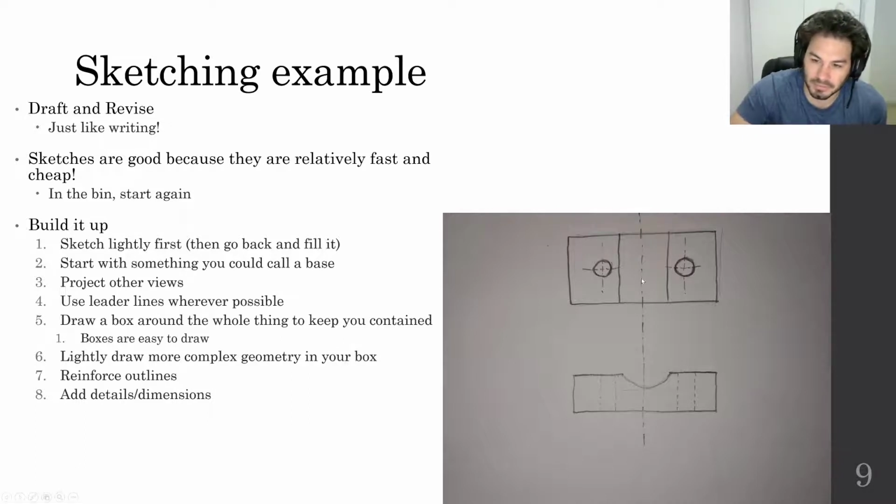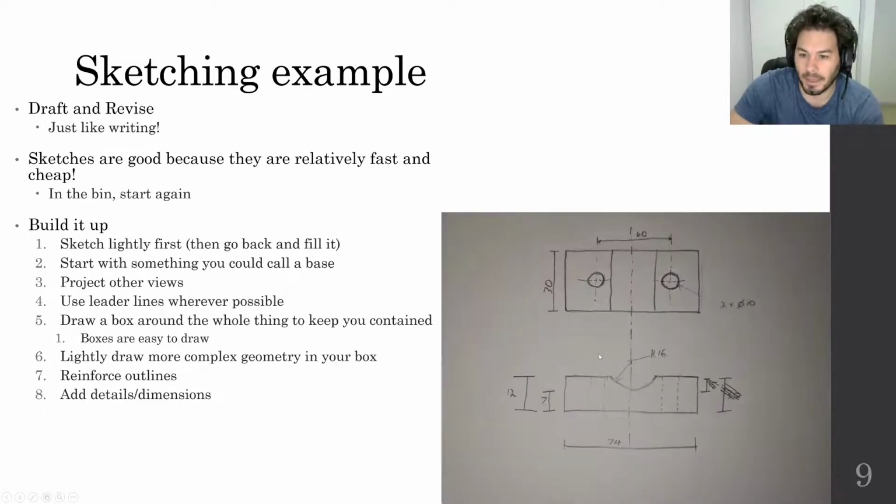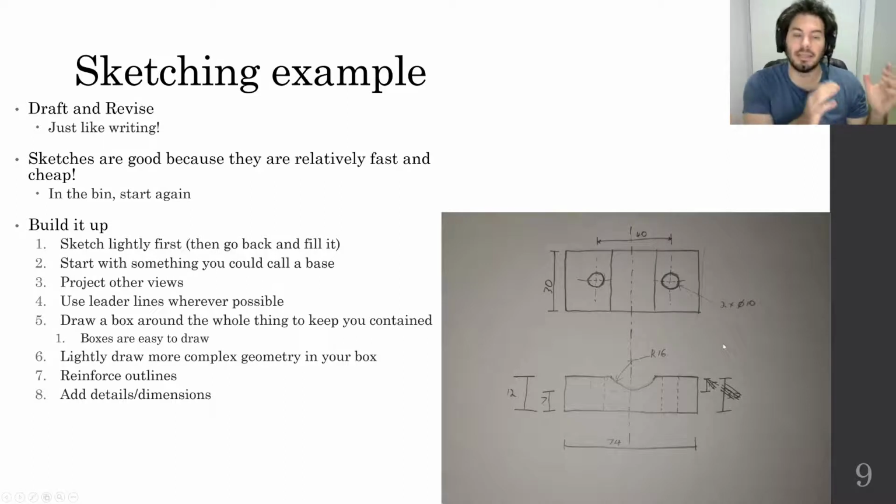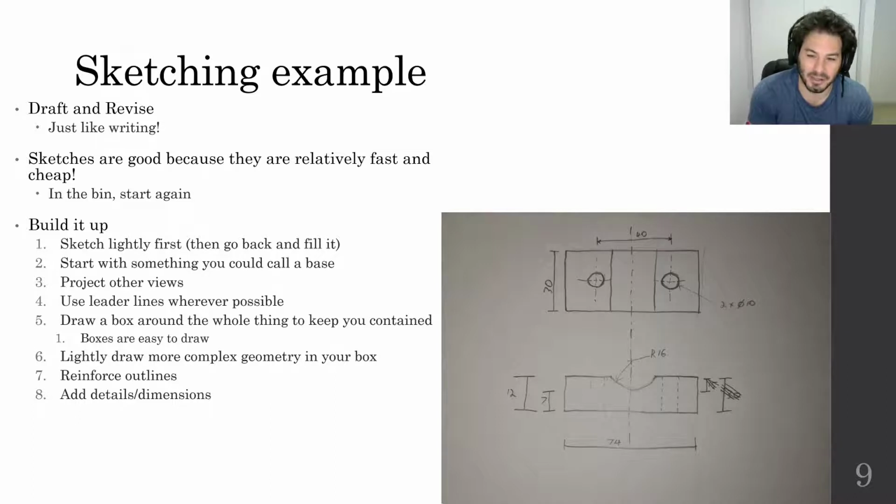So I've dumped some center lines in here, some hidden lines to represent my holes. And then I went and dimensioned it. So this would then be, I'd be okay with this. I would very happily walk into a workshop armed with just this drawing and be able to start making, or open up my solids modeling package and make this object as a result of this sketch. Meaning it achieved its goals, right? So it may not be pretty, may not be a work of art that's getting hung on the fridge by your parents, but it's effective, it does its job.